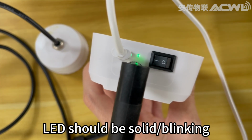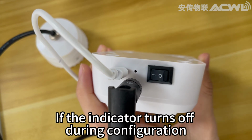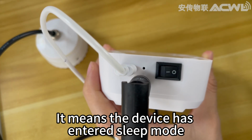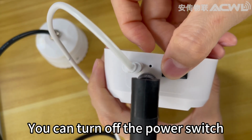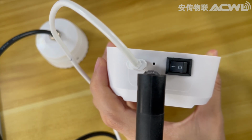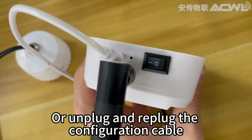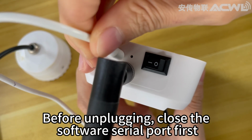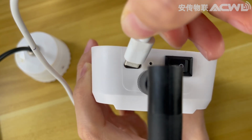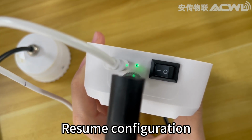Configuration notes. LED should be solid or blinking. If the indicator turns off during configuration, it means the device has entered sleep mode. You can turn off the power switch, wait 5 seconds, then turn it on again. The indicator will stay on again. Or unplug and replug the configuration cable. Before unplugging, close the software serial port first. LED blinks after reconnection. Resume configuration.